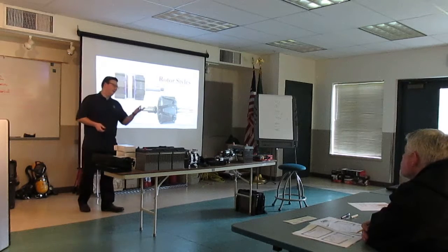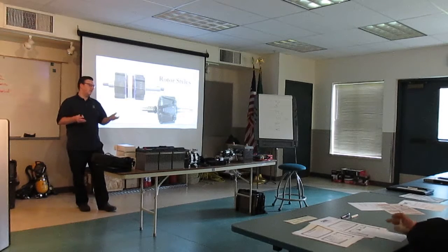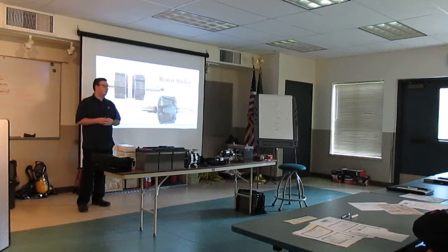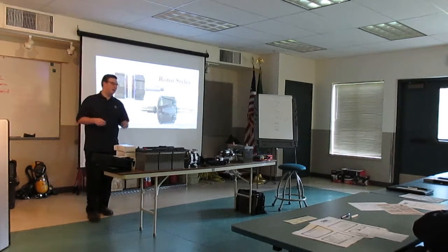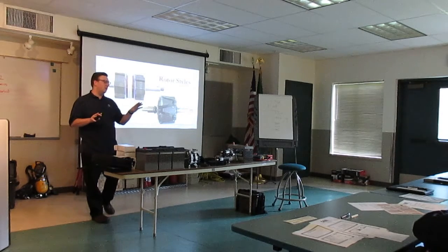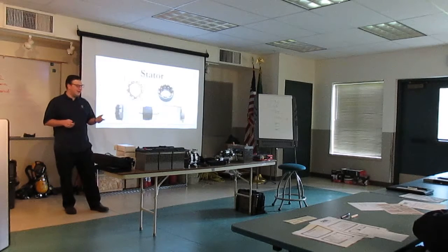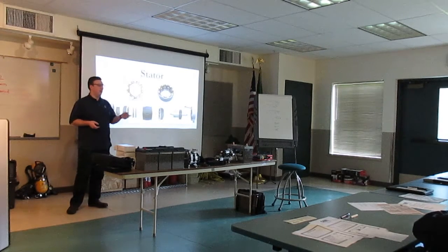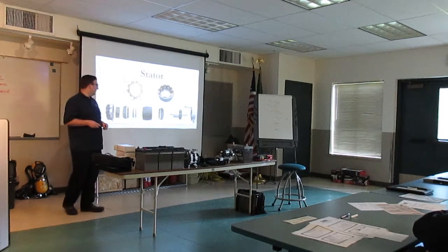The thing with the ripple is that it's subjective to each unit. On some testers, ours shows as having a higher ripple. On some, it shows a little bit lower. It just depends. Generally, when you're testing for ripple, and we'll get to it in a minute, the consistency of the pattern is more important than the amplitude of what you're actually reading.